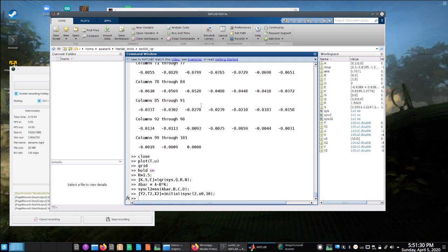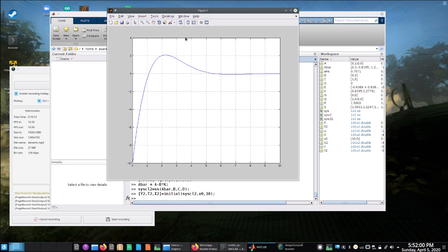We expect that if we suppress the input more, that means the system will not be able to supply as aggressive an input. So the input will be softer, so that the convergence of x to 0 will be smoother, slower, essentially. That's our expectation. And we also expect that the magnitude of the input will stay essentially smaller. Okay, here in our plot, we see that the magnitude of the input actually starts at -10. So let's see what happens in this case.